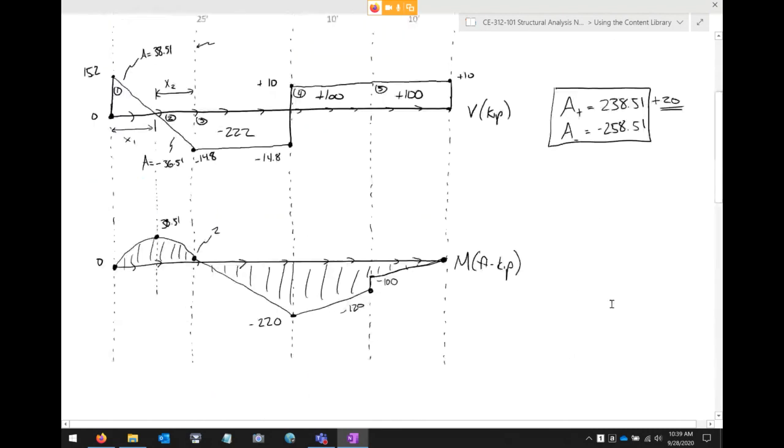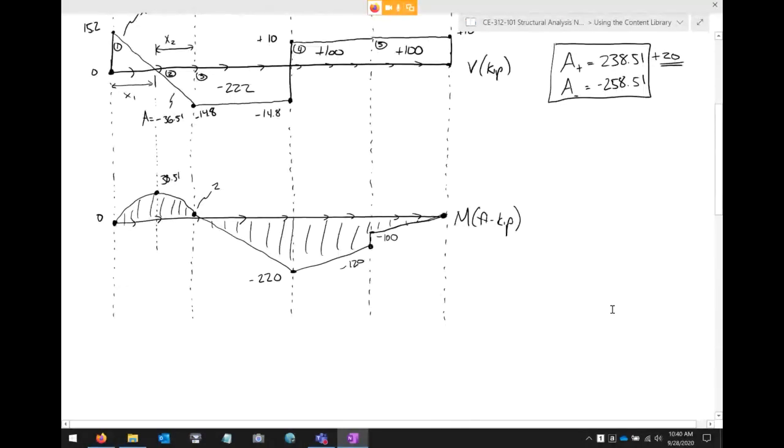Whereas if you look at this beam, what is going on with this beam? Well, most of the beam is going to be frowning at you, but some of it isn't. If you look at the leftmost portion of the beam, that left portion of the beam has a positive bending moment.